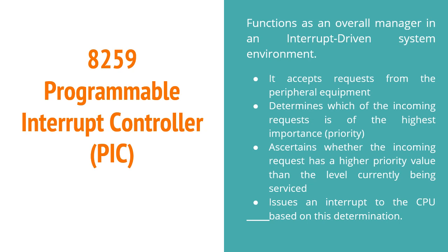Moreover, in these multiple interrupt systems, the processor will have to take care of the priorities for the interrupts simultaneously occurring at the interrupt request pins. So this becomes a difficulty for the processor. To overcome all these difficulties, we require a programmable interrupt controller which is able to handle a number of interrupts at a time. This controller will take care of a number of simultaneously appearing interrupt requests along with their types, their priorities, etc. So this programmable interrupt controller will relieve the processor from all these tasks.